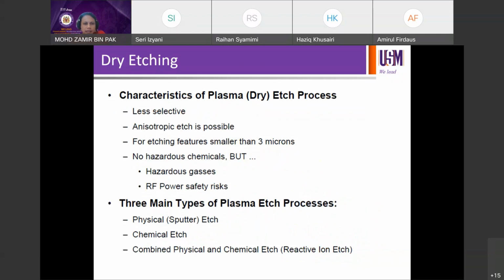So dry plasma, okay, plasma we've discussed. Plasma is ionized gas. Okay, typically we use argon, and to be able to generate argon plasma, you need to strip off the valence electrons from the argon. Okay, Ar comes in, and then you strip off the valence electrons. So that means Ar minus electron, producing Ar+. Ar+ will be the argon ion. So if you have a cloud of argon ions, then you're going to generate plasma at some level.